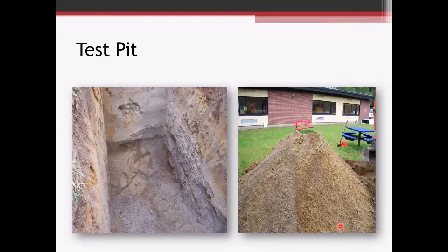But you can see from the photo that the test pits actually give you a good representation of what the soil horizons are in the test pit. So you can see some changes there, changing coloration, as well as a change there. And it looks like the materials, as you go deeper, become a little bit more coarser in nature.